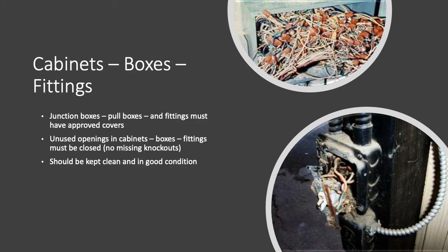Someone from TTK corrected me. I said that brushless tools are intrinsically safe. That's not actually correct. There are brushless tools that are intrinsically safe, but just because they're brushless does not make them truly intrinsically safe. So you want to make sure you're using the right type of tool for the job.